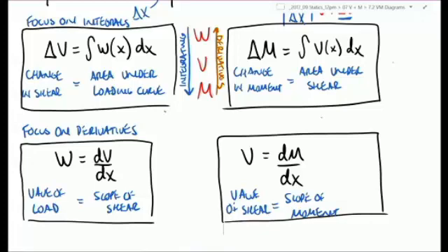There's an alternative in section 7.2 where it's very equation heavy, and even for the easiest problem, you write all these different equations for your shear and moment curves. It works equally well. It's just that even on easy problems, it's quite a bit of math. On harder problems, it's even more math. And I teach a way that if we can use this graphical technique to solve for the easy to mid parts of a problem, if it's hard, we can substitute a couple of equations in there to get us where we need to go, and then we've got all the pieces together. So it's kind of the fastest technique. I also find it has the most intuition built into it. So you can look at your functions and really get a feel for, is this right or is this wrong? Cool.